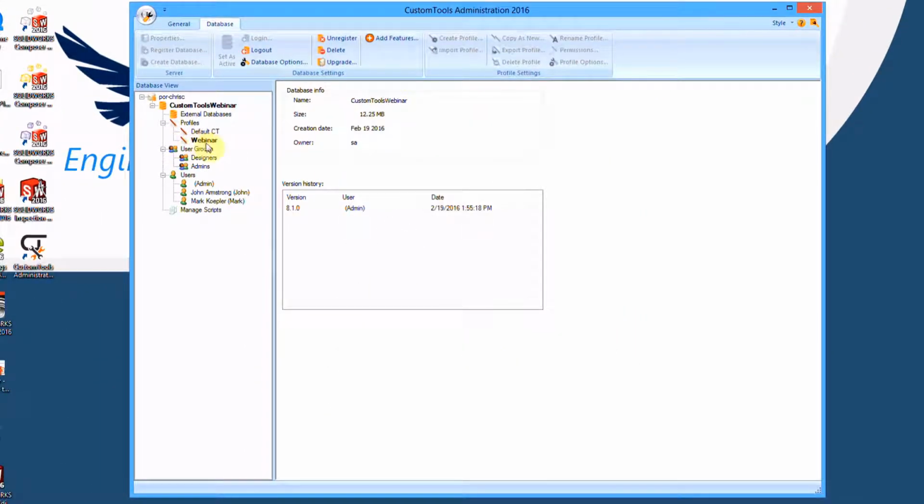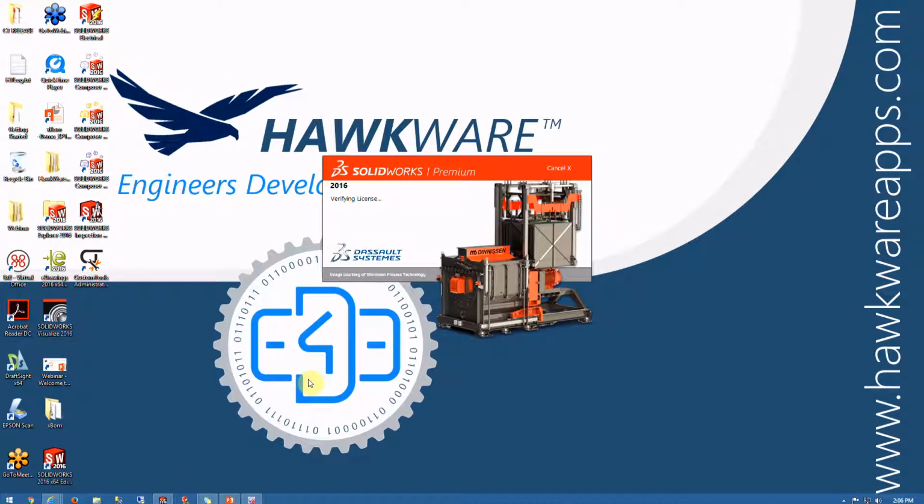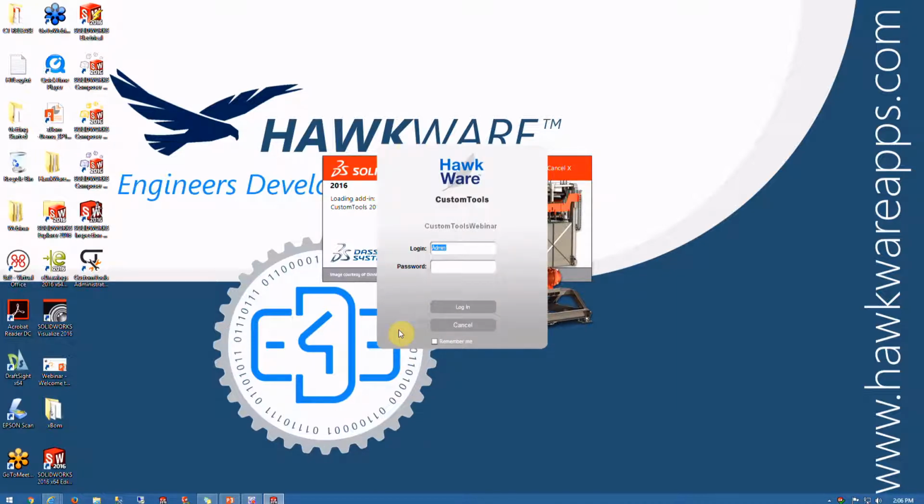And that simply means that users logging into SOLIDWORKS, logging into this Custom Tools webinar database, will be using this profile. That's what the active means. And now, since I turned the add-in on and told it to stay on, I should get a pop under. You'll notice it pops under the splash screen here. Just click on it somewhere and it'll come to the top, and then you'll log in. If you hit remember me, it won't show you this again.